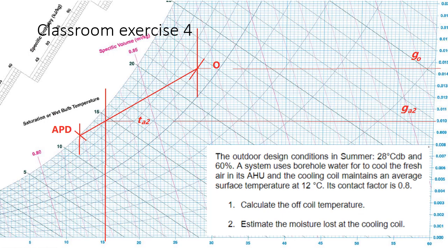So you can see for this amount of moisture content in the air at 28 degrees is only 60% saturated. And if we reduce room temperature, it becomes 80% saturation. If we reduce further to 20 degrees, it's almost 100% saturated.